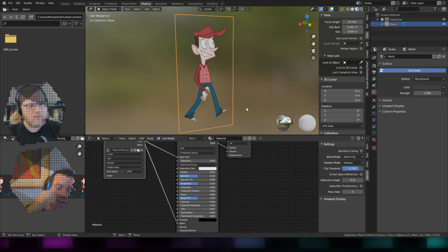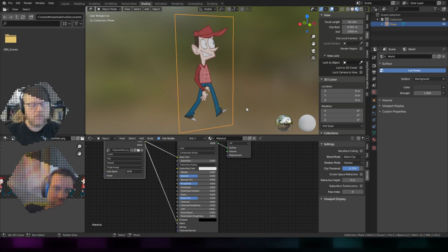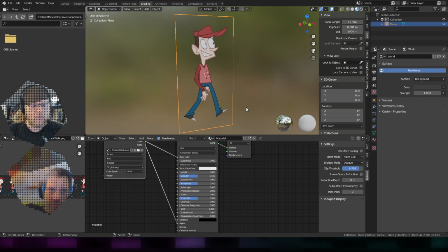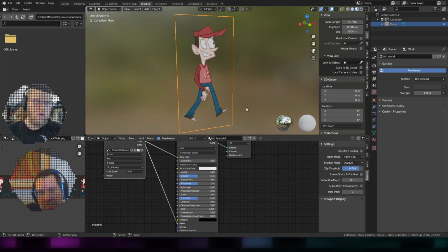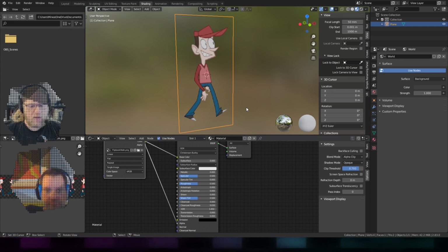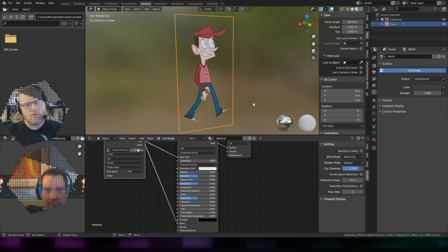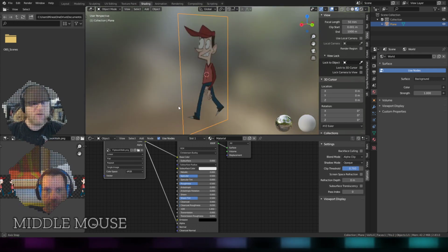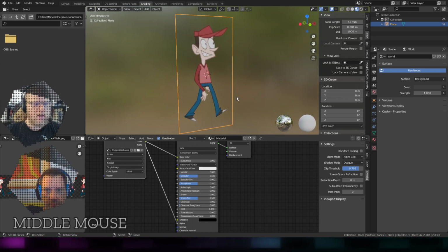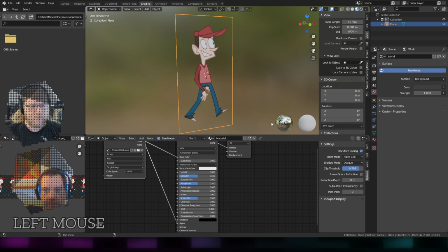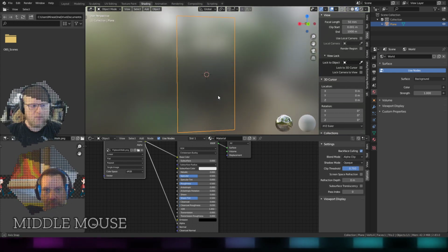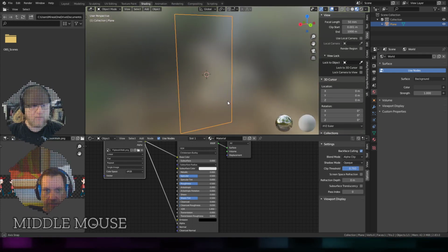But even that fire one that I showed in Hubs had all kinds of smooth alpha on it. I just set it to alpha clip, and it looks pretty good. With blend, if you want to do that, that's fine too. You just have to be aware when you're using it to make sure not to overlap it and that sort of stuff. Also, bear in mind you can turn on backface culling here so that it would not draw the back of this if you were looking at it from the other side.